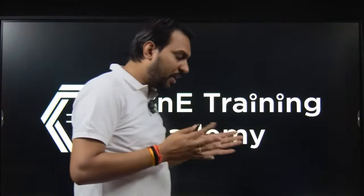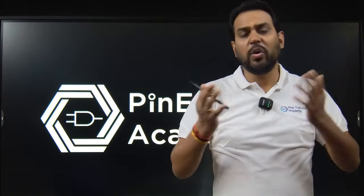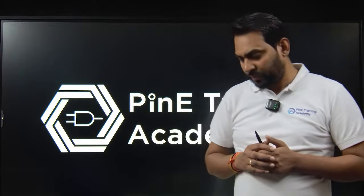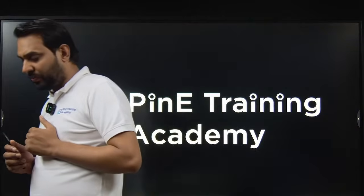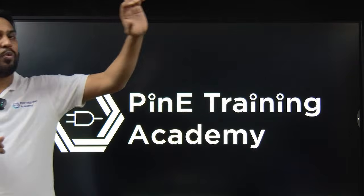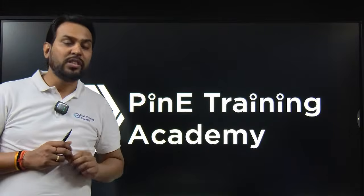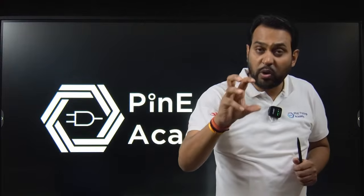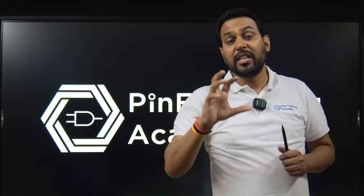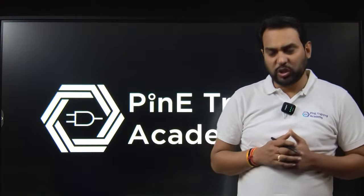In terms of voltage and current, you can describe it in four ways: voltage controlled voltage source, voltage controlled current source, current controlled current source, and current controlled voltage source. These are the four types. The voltage controlled voltage source is just like the internal architecture of the op-amp. You have a difference of inputs, Vin1 and Vin2, and you find a dependent source inside the circuit that behaves like a voltage controlled voltage source. The source is a voltage that depends on the input voltage. An op-amp is an example of a voltage controlled voltage source.